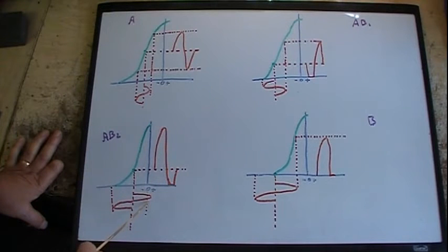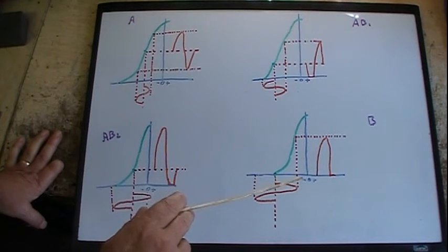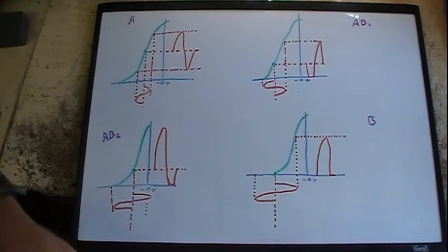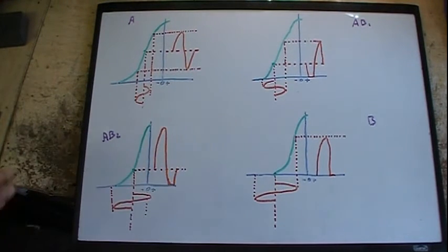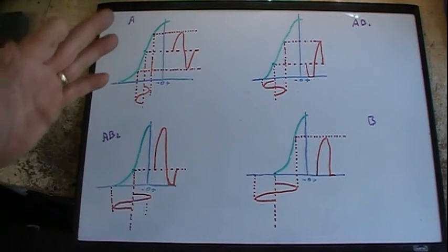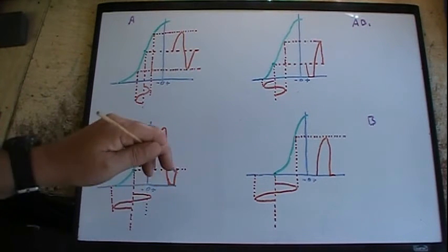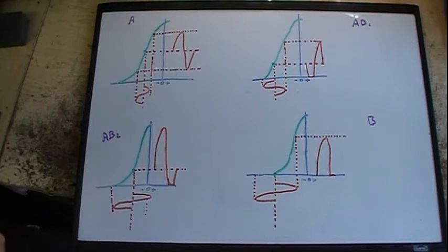So when this went into here on AB2, where the grid started going positive, strong enough signal to drive it positive, or class B, running a little bit of current on the grid, run the grid a little positive, no problem. Pull it right from that fixed bias point, and it will not affect the radio, will not affect the power supply. Everything's perfectly fine, and that's the least costly, because you're already figuring on you're going to have that in there to get your biases for different points.